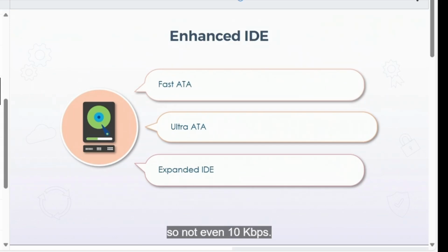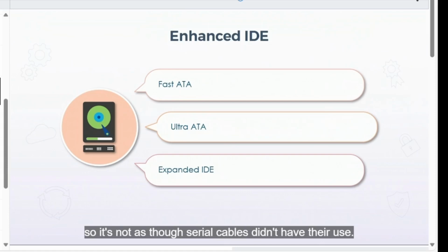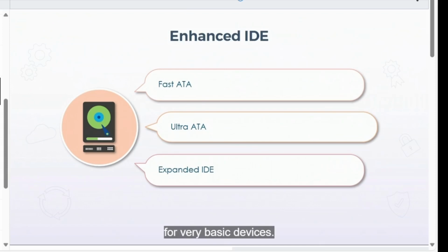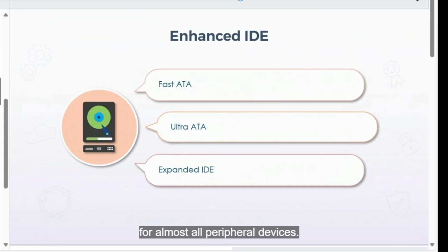For the most part, what you were looking for was simply the data transfer rate, because all IDE devices still used the same interface and the same cable. So there weren't a lot of concerns with respect to compatibility, with the exception of what your motherboard would support. In other words, you wouldn't have wanted to go out and spend money on a faster hard drive than what your motherboard would support. It would still work, but only at the lower data transfer rate.